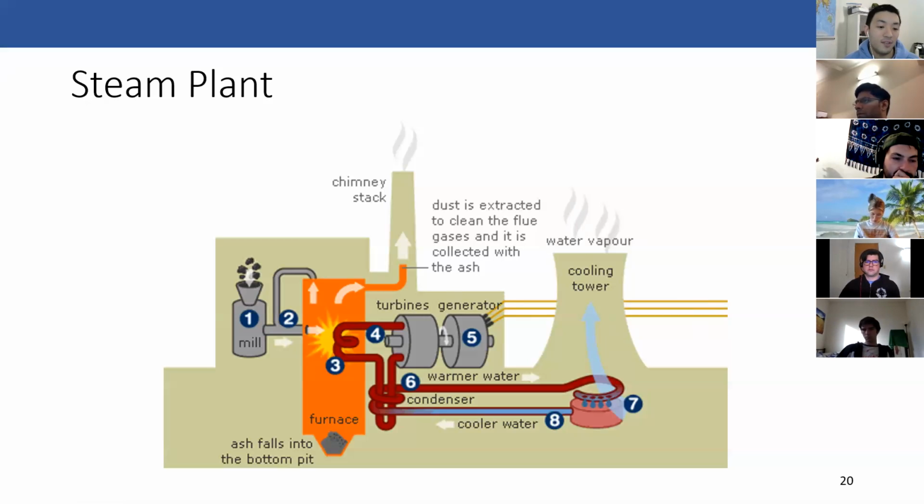And that's actually a kind of a clever way of doing it, right? Because you can use pretty unpurified water for the cooling part, whereas you wouldn't want to do that for sending water through the turbine, because you could get buildup of impurities within the turbine. But in this case, it's just cooling down the water that's being used directly in the steam cycle.